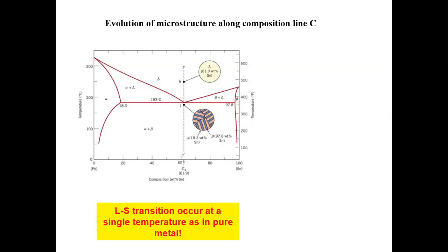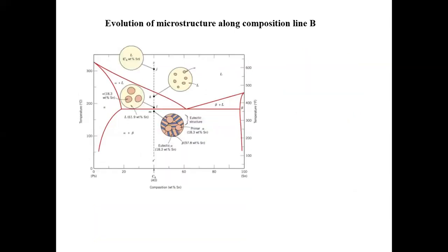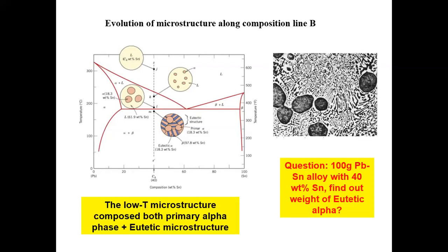And the last one is going to be along path B. So you have a mixture of these two, which generates a very interesting microstructure, but because there's no new transformation mechanism involved here, basically you just have the solidification, nucleation, growth processes, and you have the eutectic processes. Those two we will separately discuss.